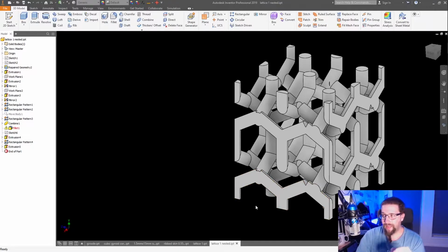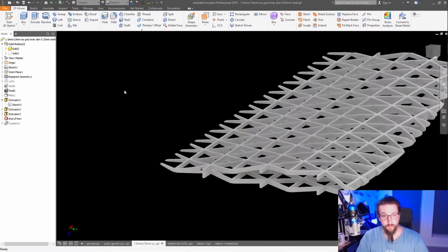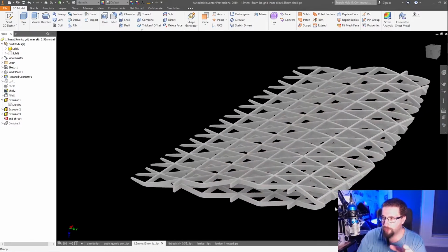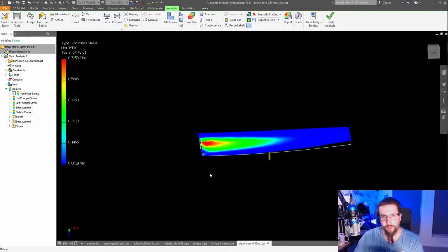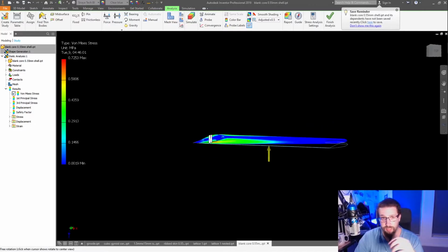In order to get the strength we need, we have to focus on doing things like smart and targeted structural generation. We have to look at what the forces on the wing are that we're going to be using and put structure there and only there where we need it. So I had to play with using FEA, finite element analysis, or stress simulations, that sort of thing.